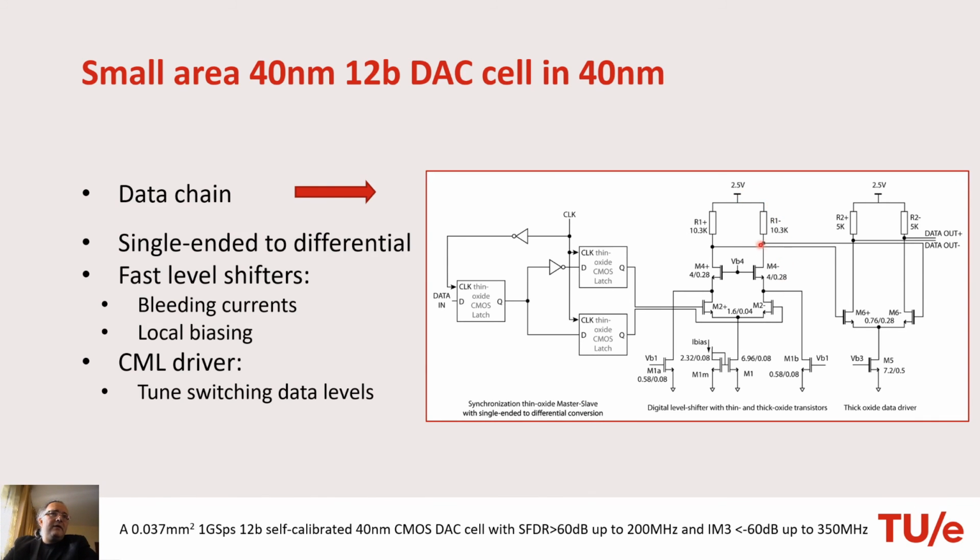Then this is fed to a CML driver, which will adjust the levels of the signal to be good for the current switches in the DAC cell.